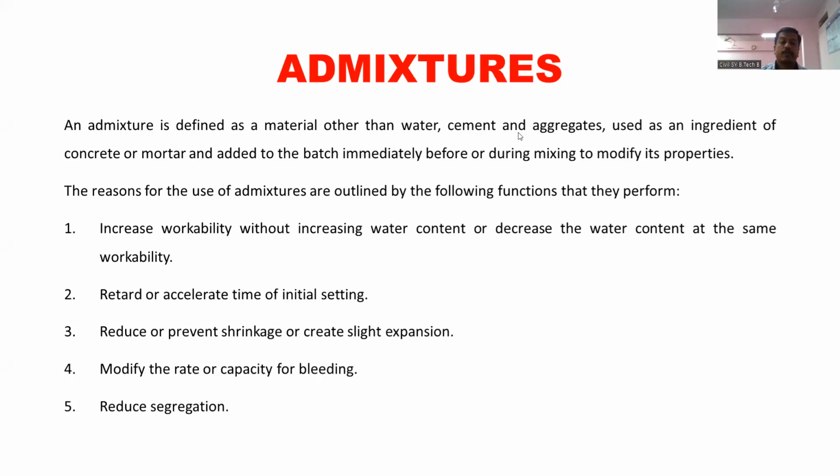So basically, we are going to use this admixture to improve the workability of the concrete we have prepared, or to improve the setting time of that particular concrete by using accelerators or retarders. Accelerators we use to accelerate the rate of heat of hydration, and retarders we use to decrease the rate of heat of hydration.